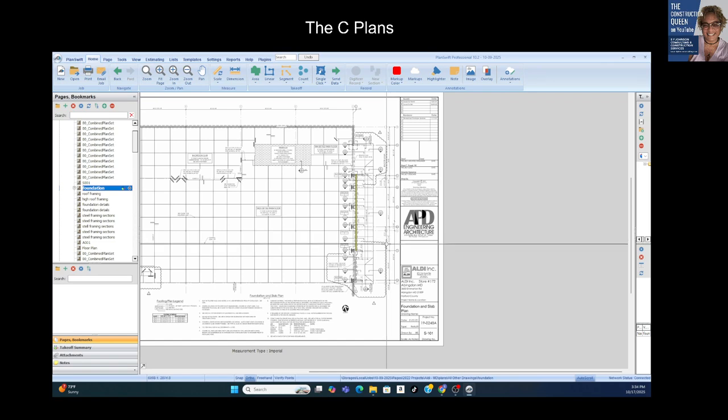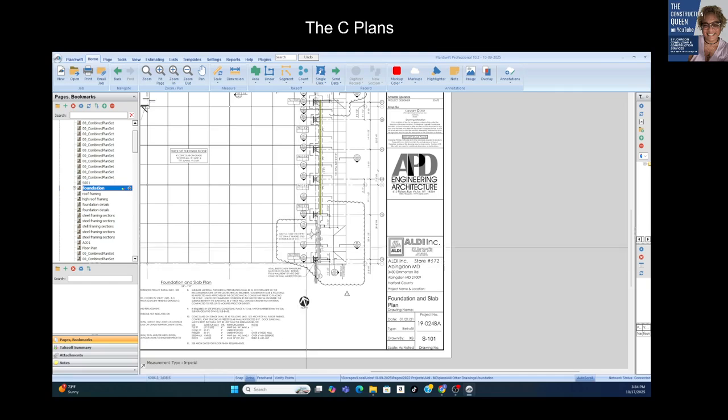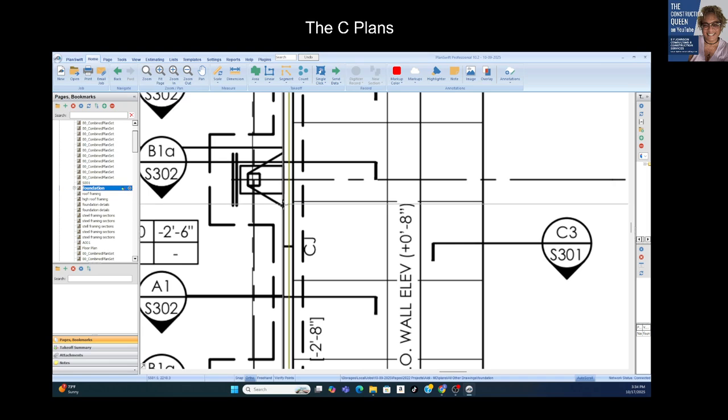So a foundation is pretty much three components: the slab on grade, the continuous footer, which basically is the perimeter, and all of the section views outline where we have to go to get details about all the configuration of what here is representing a foundation footing. Okay, so how do we know the component parts in a structural set?